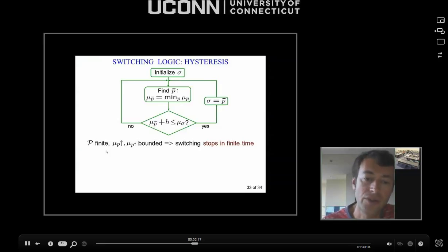Another thing, and this relates to the question that you were asking me yesterday: this result requires that each monitoring signal mu p be monotonically increasing. So if you take the monitoring signals to be the L2 norm of the estimation errors, this is verified. But if you were, for example, to use the estimation errors themselves, which dance up and down in an arbitrary fashion, then this result wouldn't be applicable. So it does require certain care in defining monitoring signals.